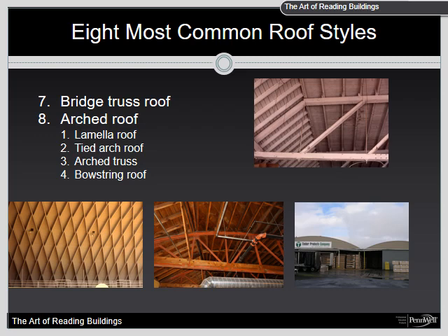This type of roof can predictably fail in sections depending on the type of fire. The strong area is at the perimeter of the building. Hazards. Its strength is dependent on the size of the lumber and the span of the truss. The trusses are in compression and tension and can fail under severe fire conditions. The underside of the roof is usually exposed in warehouse-type structures. Due to their age, roofs are likely to have multiple layers of some sort of composition material.